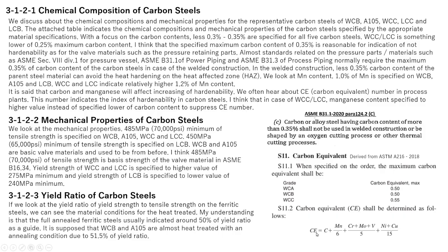Carbon equivalent equals carbon, which is a very effective hardenability element. Second is manganese. Manganese is also a hardenability element, but the coefficient is 1/6.